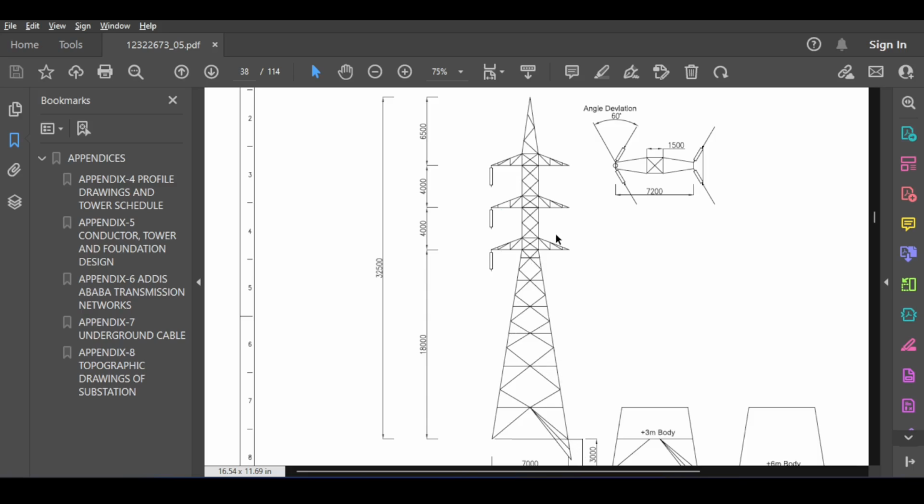Now, you could model it to be one full piece, but please notice that due to practical limitations, you might not have pieces that are 18 meters long from factories. You might have to splice your piece. In other words, you are now forced to cut your chord into two pieces, not because it's structurally relevant.